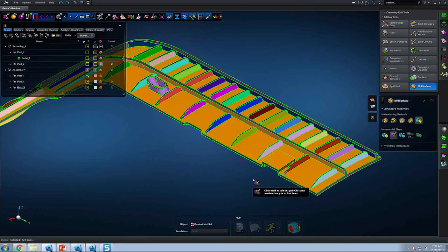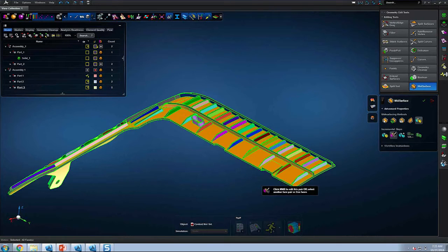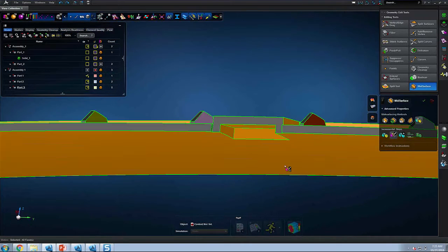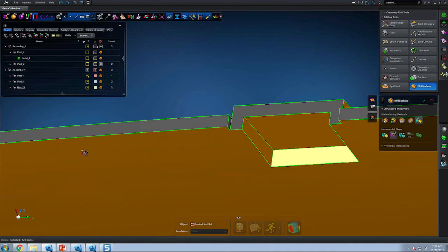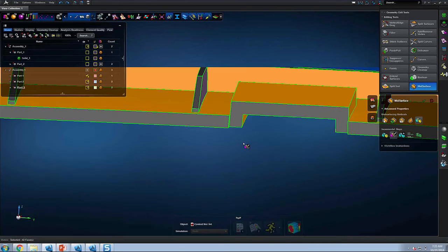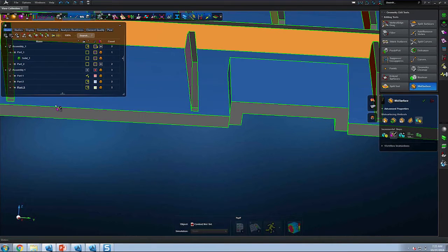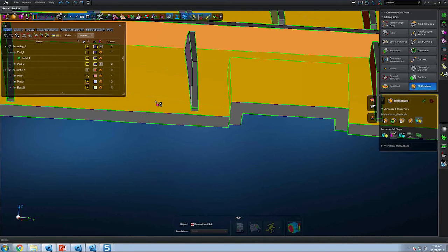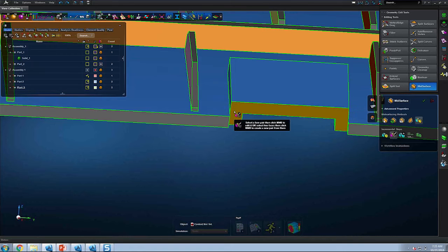Again, you want to have pairs that are using opposing ends. You also want to prevent situations like this where you have pairs that run in one direction and then all of a sudden turn 90 degrees and run in a different section. Here's one such scenario. Here in blue, you find that when it extracts the midsurface, it encounters this almost 90 degree section here.